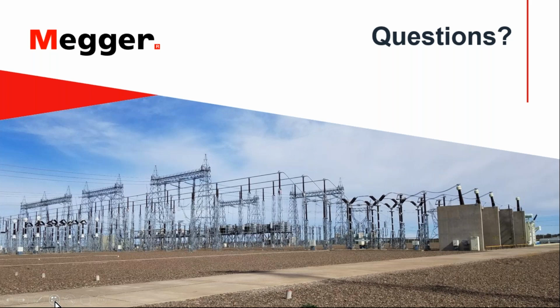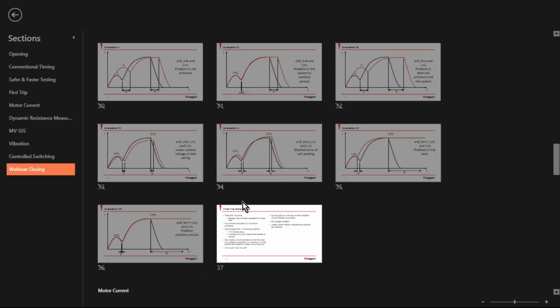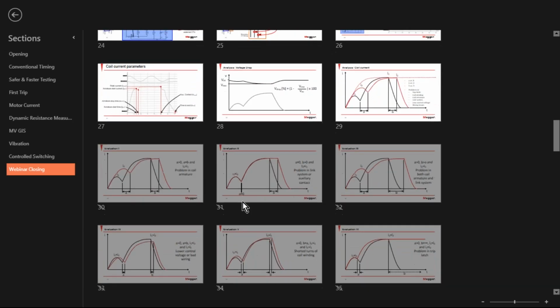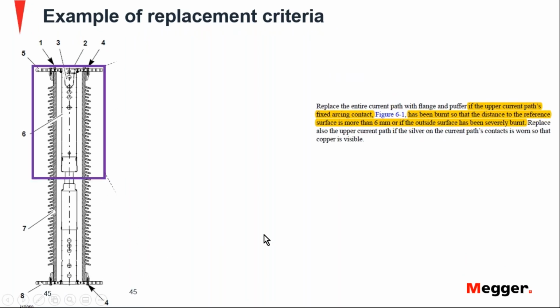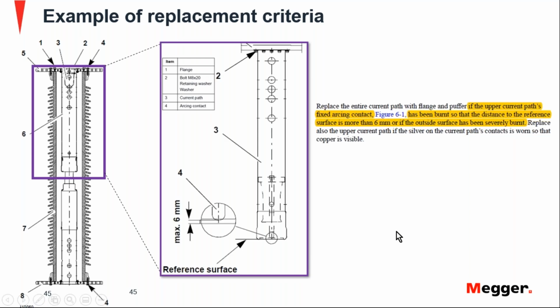What you get is a measurement that you can compare either to previous measurements of the same breaker, same pole, or if it's the first time you're using this technique, you can compare the length that you get on each phase versus the other two. Right? So again, you are not measuring it against the main contact, but comparing to the other phases. You get the measurements for each phase, but there is no rule of thumb that would apply for all breakers.